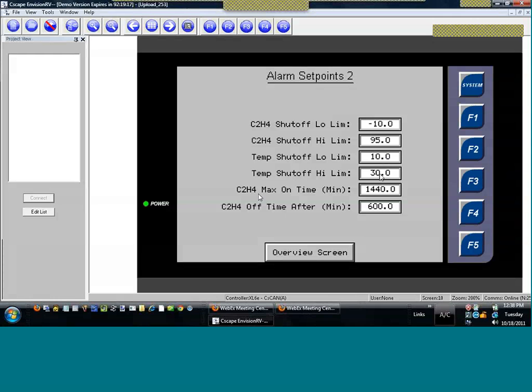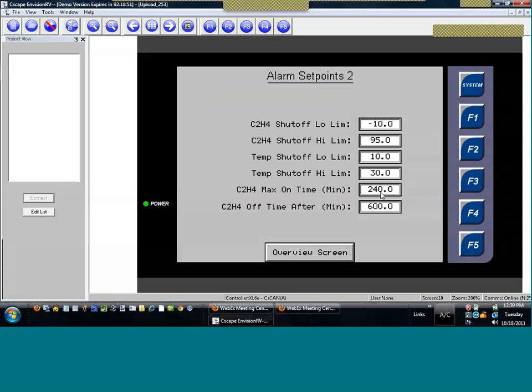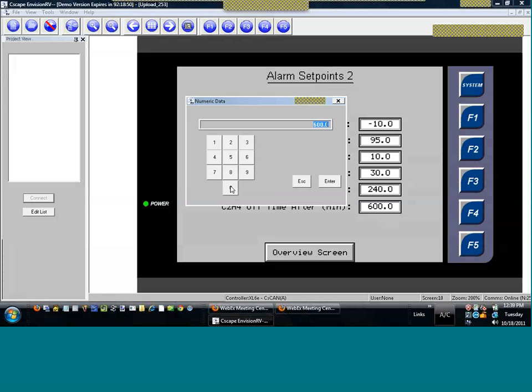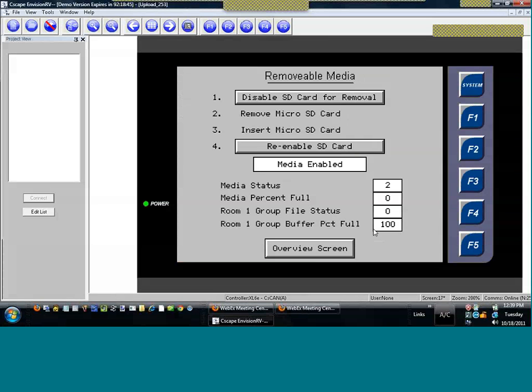And then if we call for gassing to set point for more than a day, in this particular case, and we never achieve our set point, we stop gassing, and in this case for at least 10 hours before we start again. This could be too high, and maybe we want to say if we gas for more than 240 minutes or 4 hours, we'll stop, and we'll stop for at least 60 minutes or 1 hour, but there's a safety.